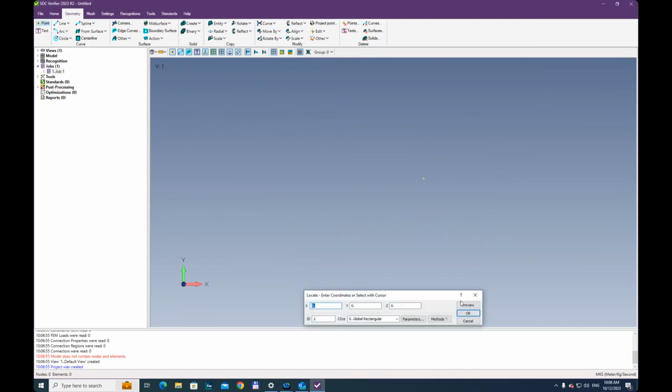And if I press OK and then close this window, you see that where we had the center, the yellow point has been created. What else we can do is create another point, let's say with coordinate 0, 0, and 3 meters. This system is unitless, so it doesn't matter what value you type in here.